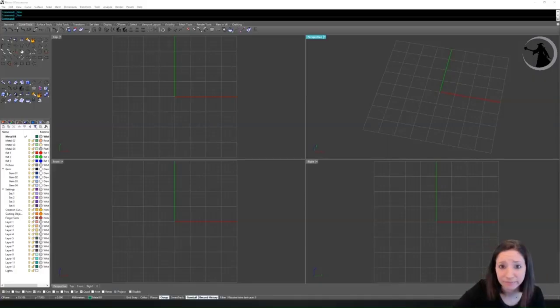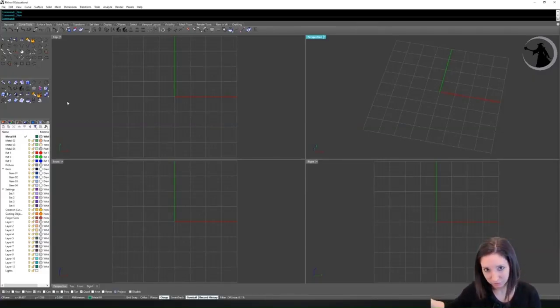So we're going to make a ring. Let's make a size 5, which is 15.76. Now, when you're thinking of making jewelry, I'm typically going to start with curves, which are just the lines. Then I'm going to make those curves and change them into surfaces. And then I'm going to take those surfaces and change them into a solid. Now, that isn't always the steps that you're going to go through, but I want you to be thinking about, basically, you're going to start with a curve, then move into a surface, then move into a solid. So that's a basic way to think about making a ring in CAD.